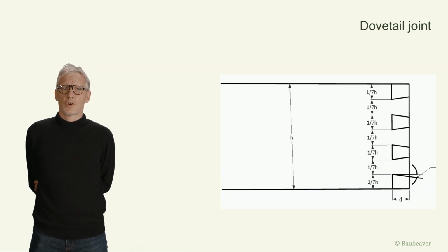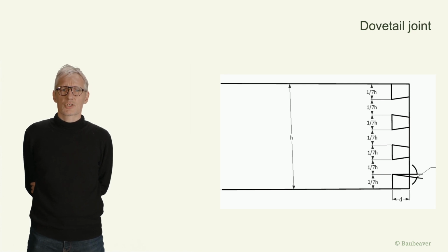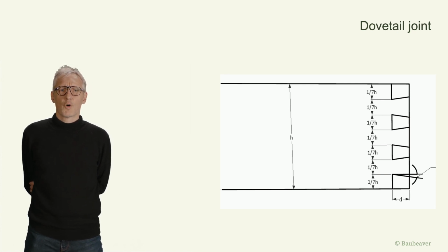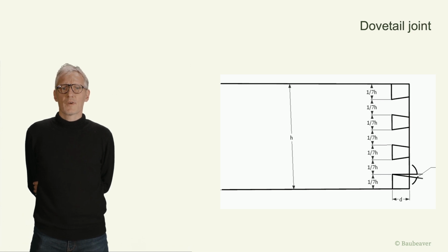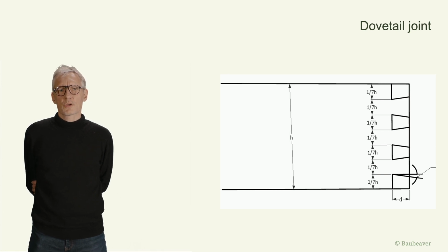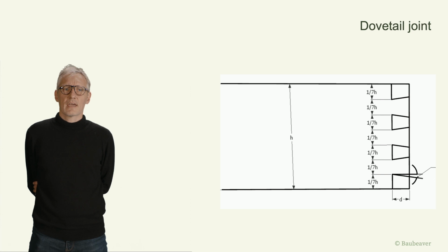The dovetail joint is probably the best known and most complex connection. Because of its form and the many contact surfaces, it is one of the most stable connections. By this connection, two boards meet at their edges at a right angle and are virtually interlaced.